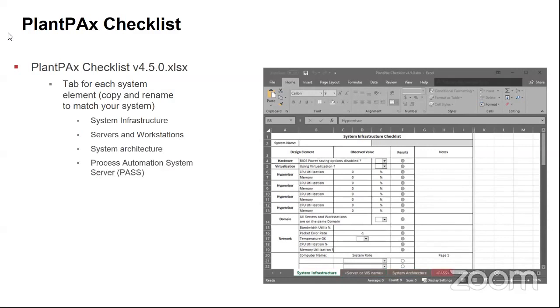How you set up your HMI server, so where you have your directory, where you have the alarm and events, all of those bits and pieces. How many displays are you using? How many clients are you using? And then tie into the controller. A lot of this will tell you how to get the information. Some of it is just going to be a visual. There's a little faceplate that pops up on the HMI, and it does all the readouts of system variables. You type that into the Excel, and it automatically does a macro to tell you where you are.